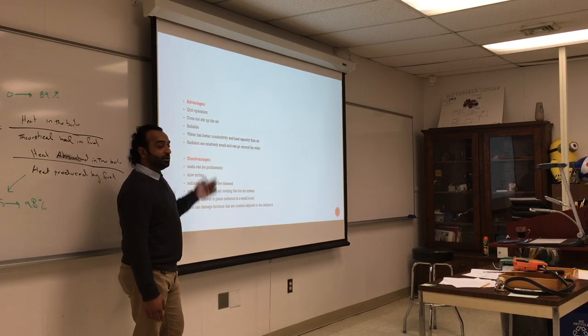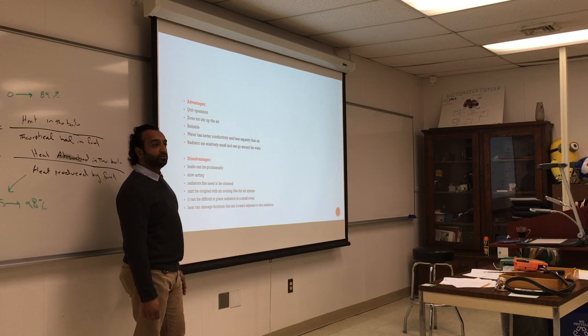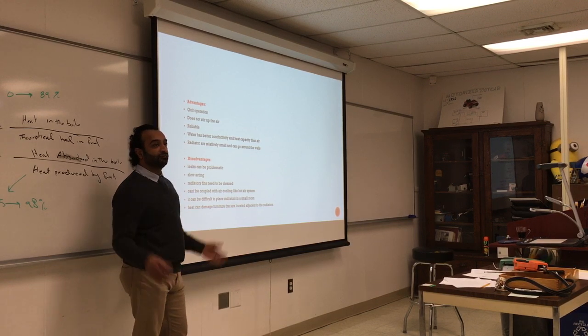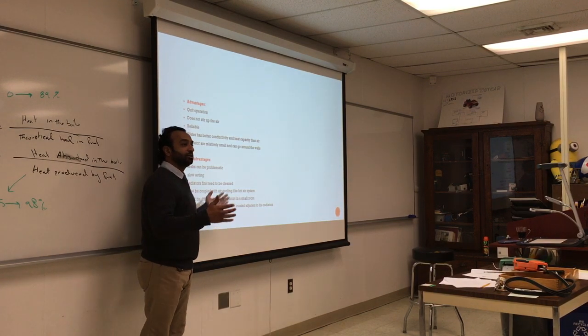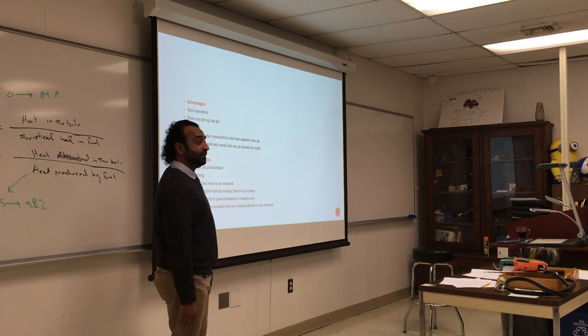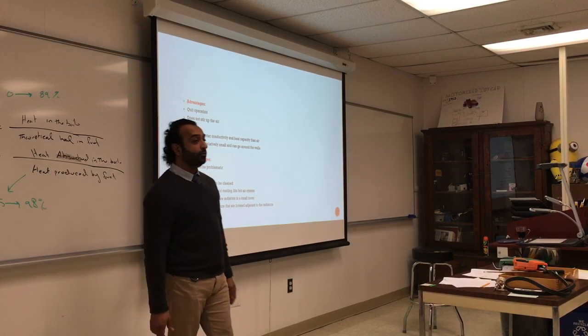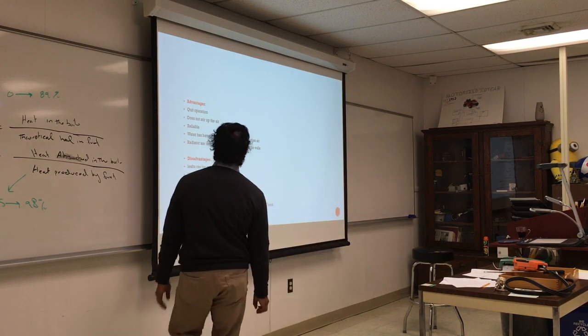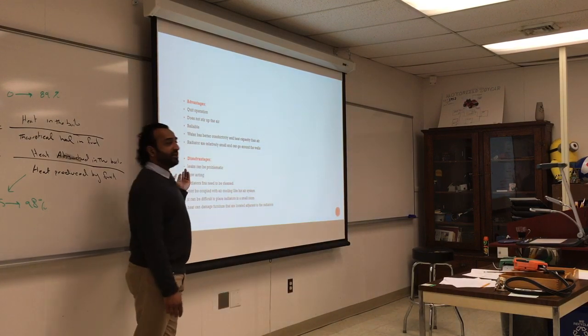So again, it depends on the situation and how big a space you have. And probably you notice in a small kitchen or a small bathroom, it's very difficult to put a radiator there. You have limited space. Also in bedrooms, you have limited space. You have a bed, a closet, dresser, etc. So probably you'll be limited by the space underneath the window, and most likely you'll end up blocking the radiator, so it does not function the way it's supposed to. Some disadvantages of hot water, yeah.